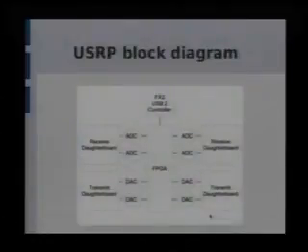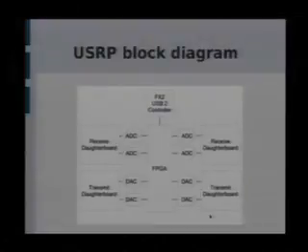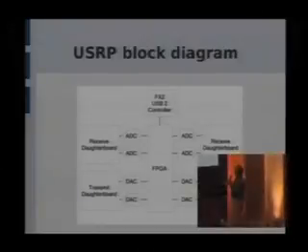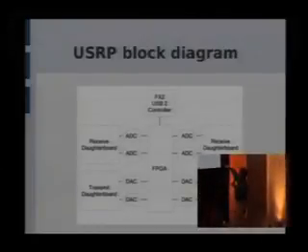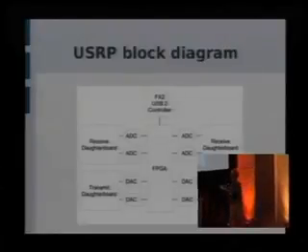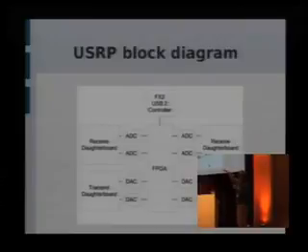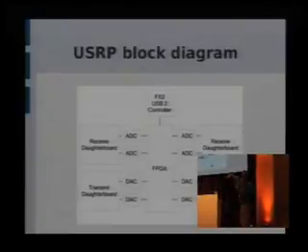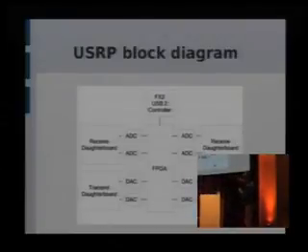It's sort of the same block diagram here. There's these receive daughter boards, the converters, and the FPGA in the middle. We do some of the signal processing on the FPGA, basically channel selection and filtering. And it hooks up over the USB 2. Everything in the system is downloadable over the USB. So we load the firmware into the USB 2 controller over it, and then we use that firmware to load the contents of the FPGA. So it's completely flexible.